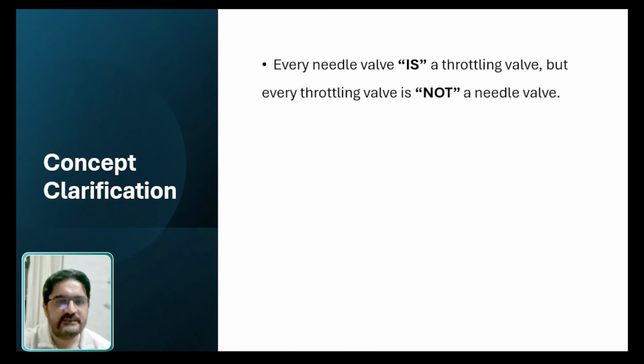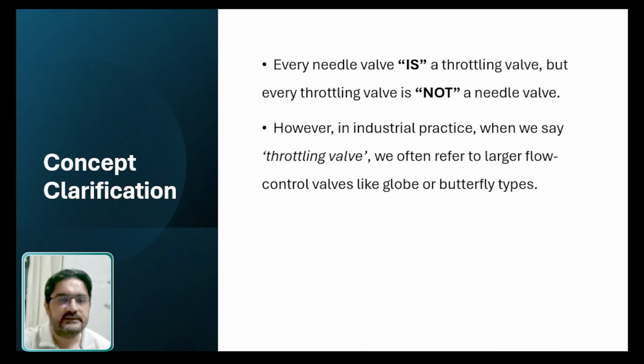So let's begin with a quick clarification first. Technically, a needle valve is also a throttling valve because both control flow by restricting the passage of fluid. However, in industrial terms, when we say throttling valve, we usually refer to larger control or globe type valves or butterfly valves, which can help in regulating higher flow rates.